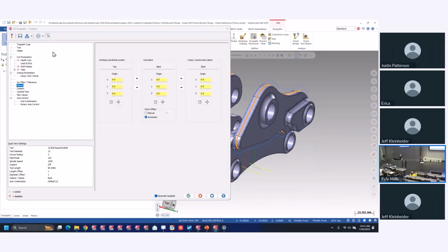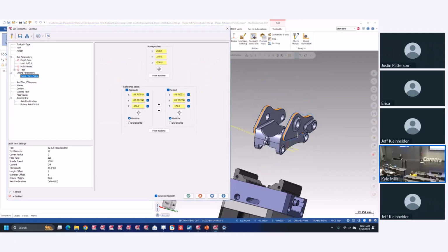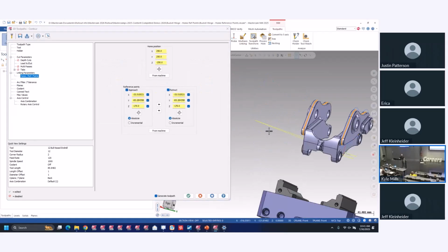My toolpath there. And you'll see already that I'm plowing through my part because it's going to that same spot, right? It's going off the WCS. It's going off the absolute. So of course it's going to go over there. So what I'd have to do in this case is, you know, maybe just flip a few of these around. Maybe I can just flip these to like positive numbers or something like that. Or maybe I have to pick a new point.